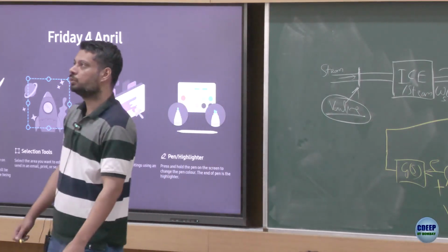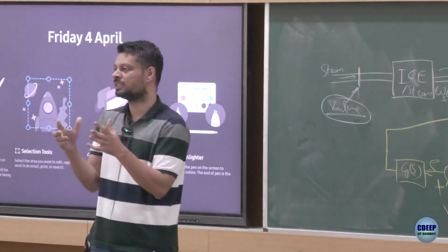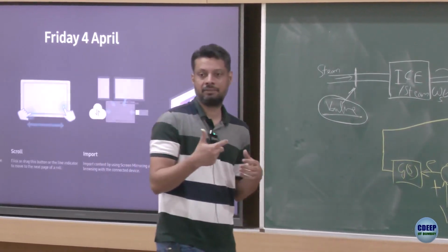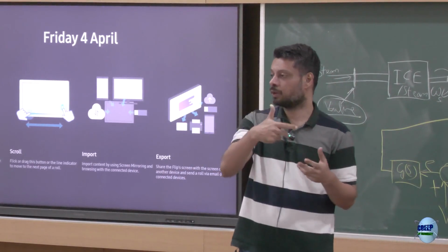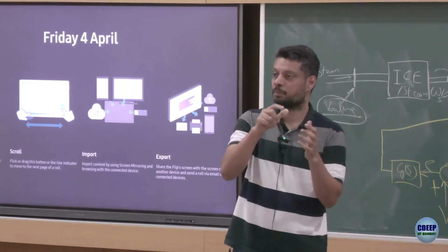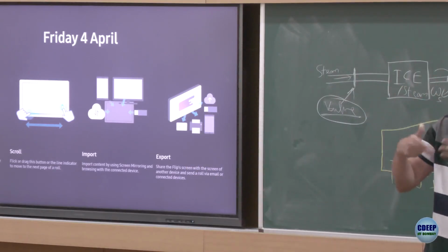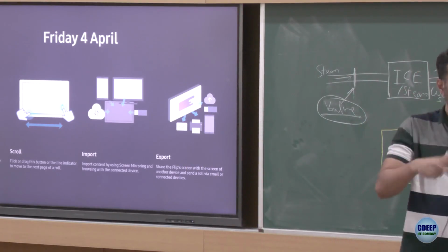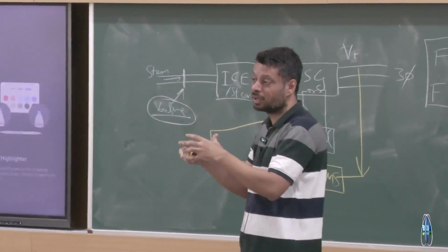So usually when you do this, maybe you have not done, but when you do this, any control system which has multiple inputs and multiple outputs, right? At a very basic level, first you try to identify which input has more impact on which output, and then you try to control that particular one with that one, right? In reality, there are much more complex control where you can take both inputs together and sort of write state space equations and then control both outputs using the input together.